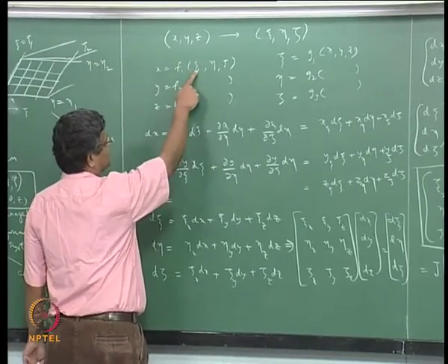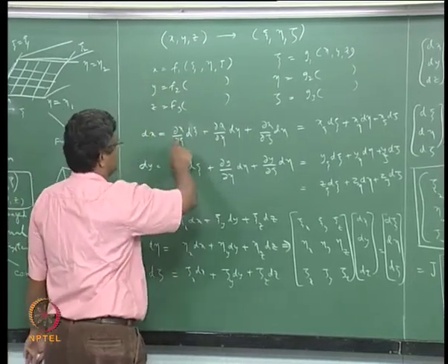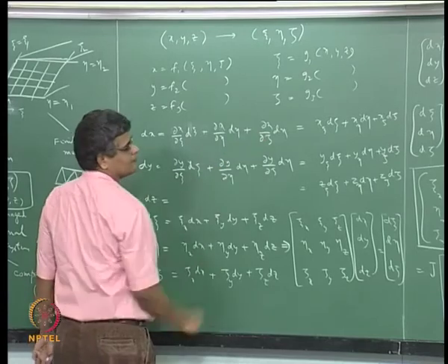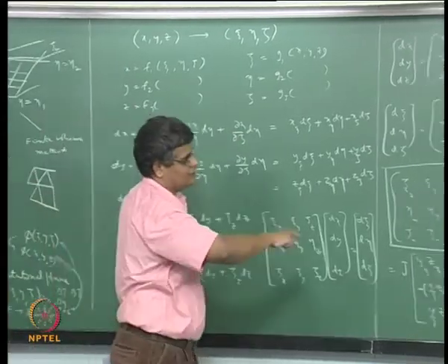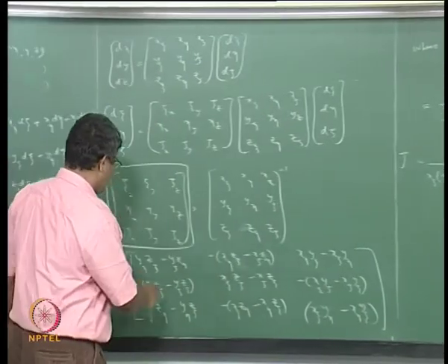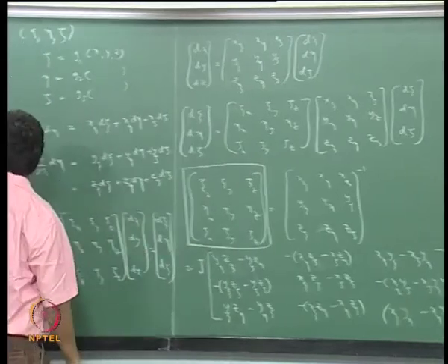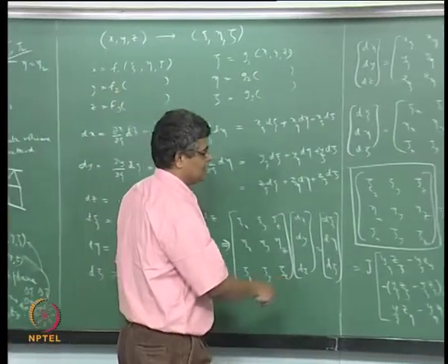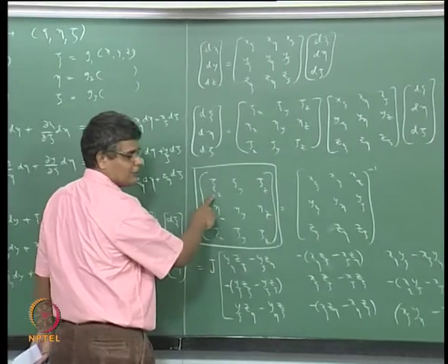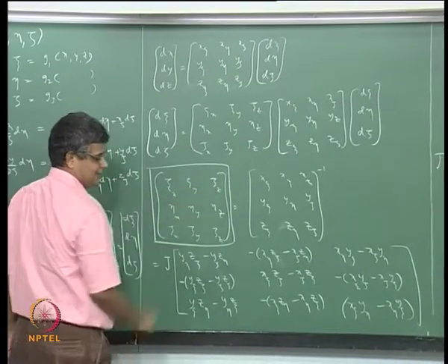differentiate this with respect to psi, eta and zeta and evaluate these metrics, and from this we can get the Jacobian, and these are already derivable from the known transformation here. So we can therefore get the corresponding matrix of psi x and psi y and psi z like this.